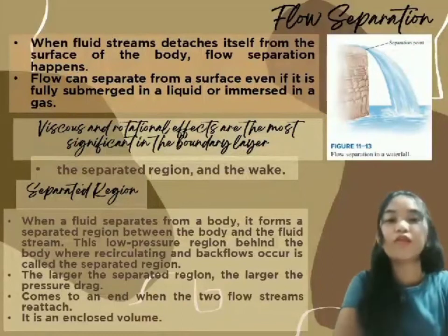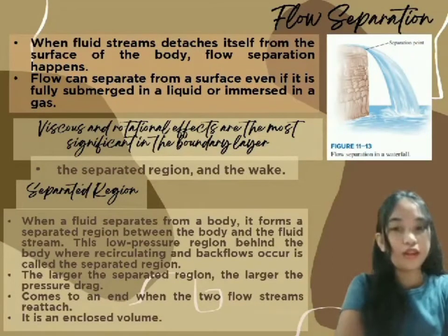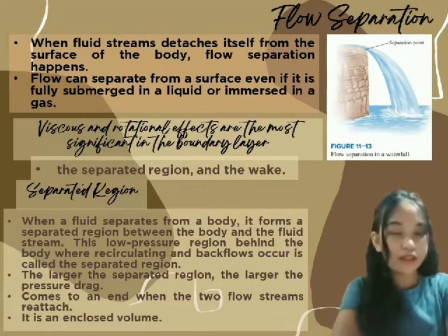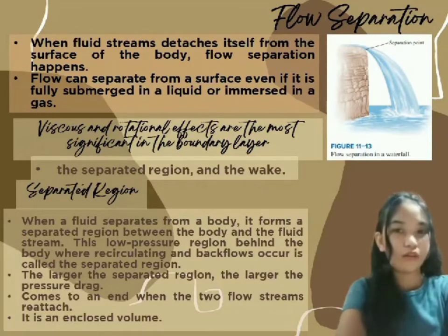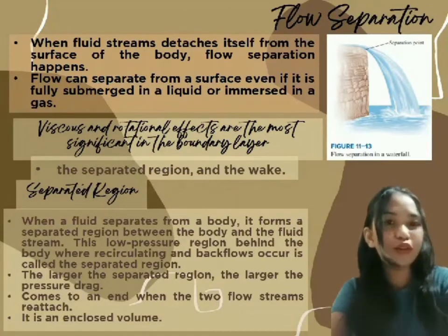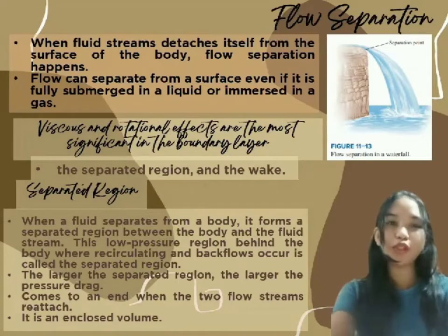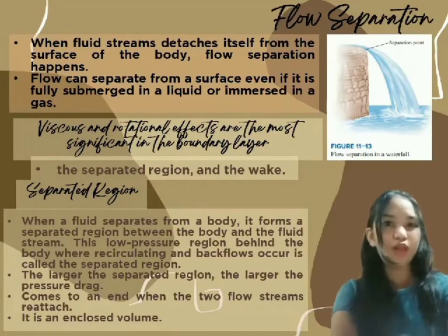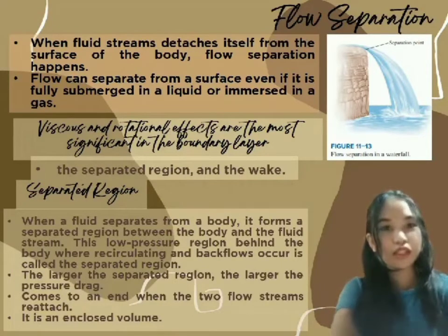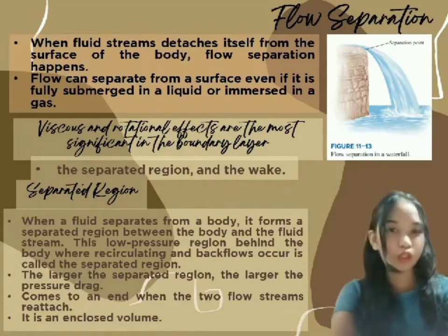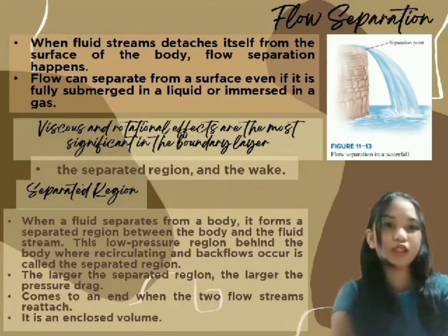So we must get familiar with boundary layer creation in order to comprehend flow separation, which I trust you are already aware of. So when forced to flow across a curved surface at high speeds, a fluid responds in a similar manner. The front part of the curved surface is followed by a fluid with no issue, but on the back side, it struggles to stay affixed to the surface.